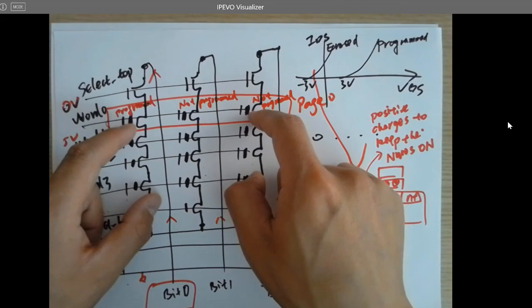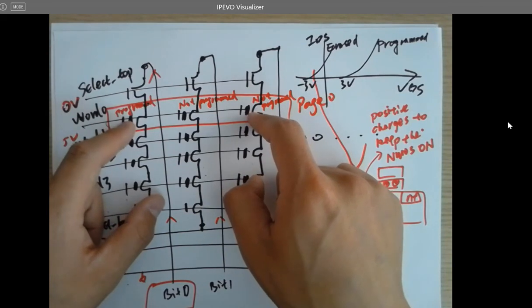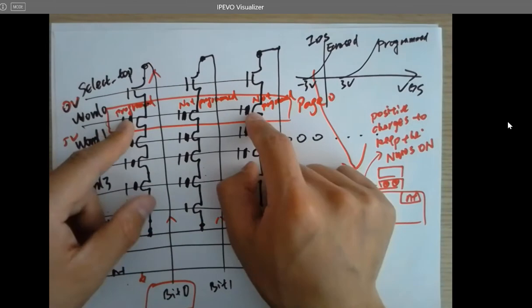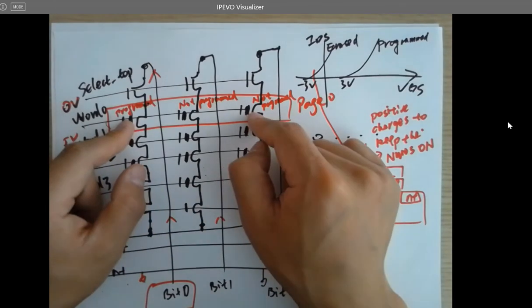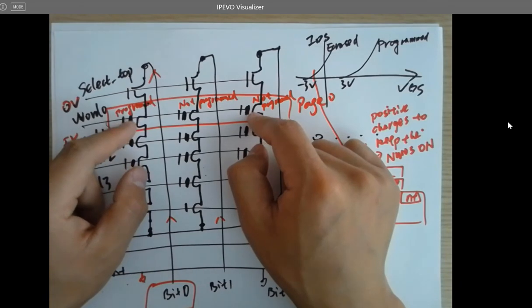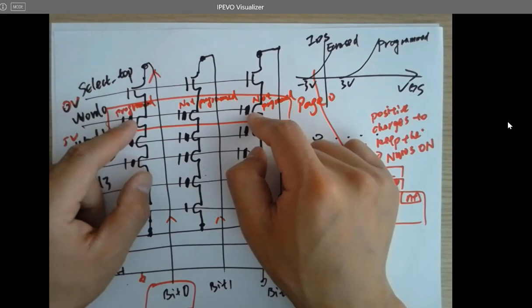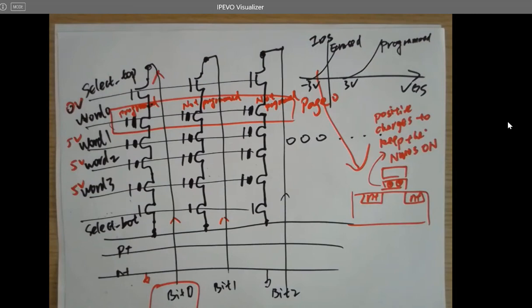So you get a memory cell. It's memorizing the state by using the floating gate. Okay, so it's not a cap like DRAM. It's not like a positive feedback like SRAM. The DRAM and SRAM both need power supply. So that's why they are volatile. For this one, it doesn't need a power supply.